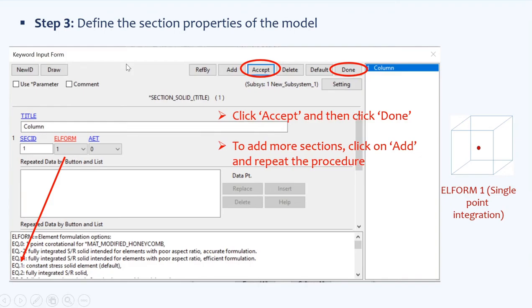One more thing. In yesterday's problem, we had to provide the thickness of the shell because we just created a plain element. We did not provide any thickness for the element. But since for our brick element, the solid element, we already have all the dimensions, we don't have to input any of the cross-sectional parameters here.